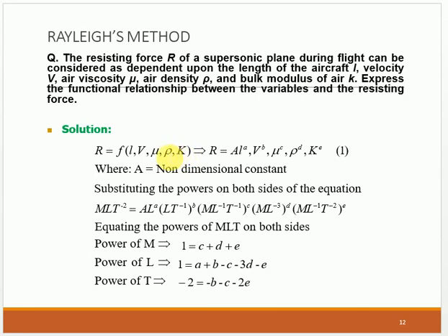So that's why I say if it goes beyond 3 or 4, it becomes more laborious and very difficult to equate the equations. I'm just giving this example to show that it's difficult to do dimensional analysis using Rayleigh's method when the parameters are more than 5. So we have the Buckingham pi theorem, which is a simplified version. With any number of variables we can use the Buckingham pi theorem. I will come up with another problem where you will understand more clearly.